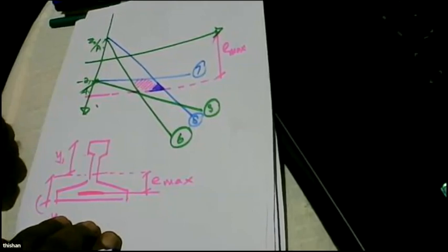It has a higher I value, and because of that, the effect of live load stresses will be less. So we have an advantageous position because of the composite action.